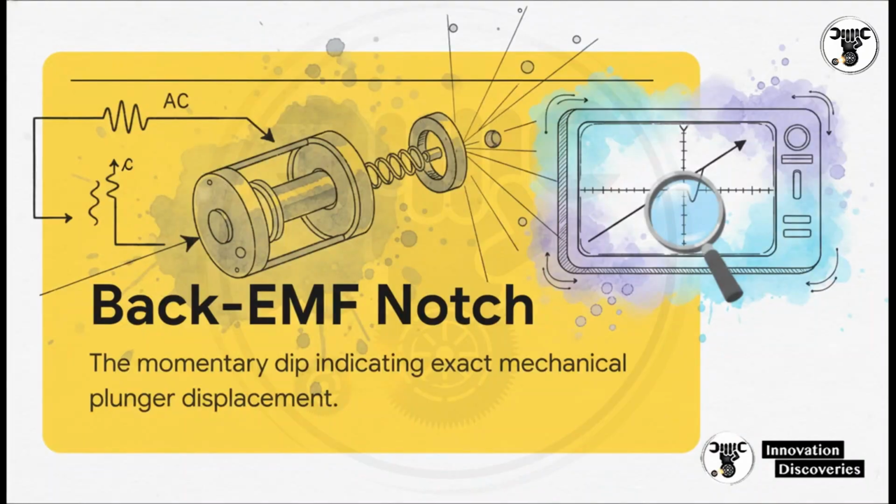So, what are we looking for? The back EMF notch. This is that characteristic knee or tiny little dip you'll spot on your current ramp waveform. It illustrates the exact microsecond the metal plunger physically moves inside the coil. As it moves, it changes the coil's inductance, creating a momentary magnetic disturbance, a back electromotive force that we can literally see on the oscilloscope screen.